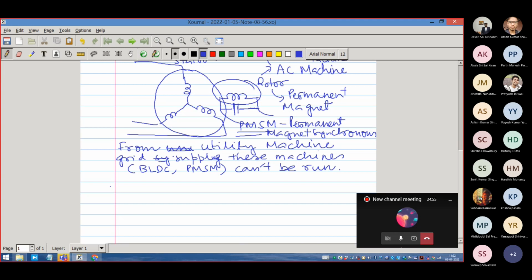niche applications, very important applications. They are called servo applications. Servo applications are those applications where position control becomes important. By the way, all the machines that we'll be talking about from now onwards, we expect them to do speed control or position control. These are the application requirements. These are applications where you want the machine to run at a certain speed.